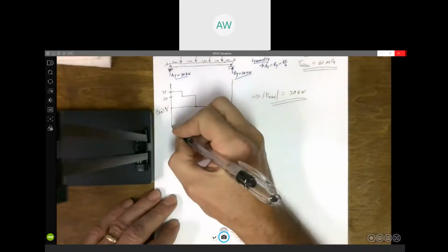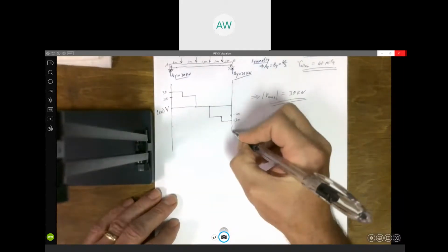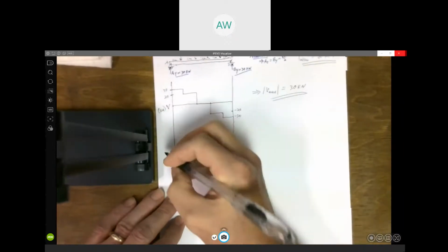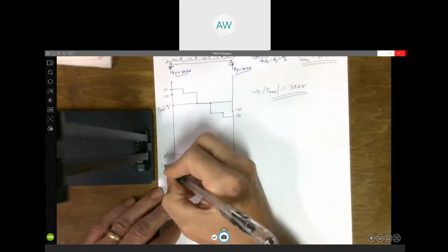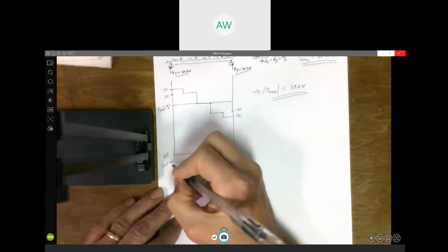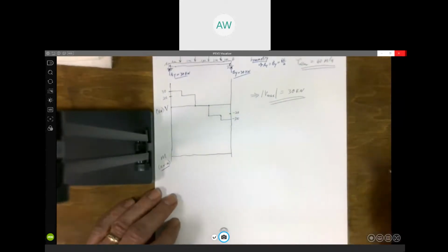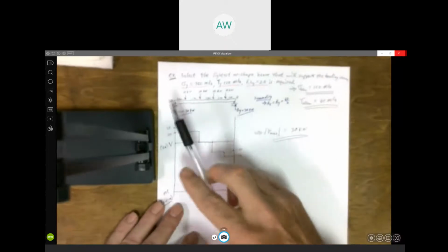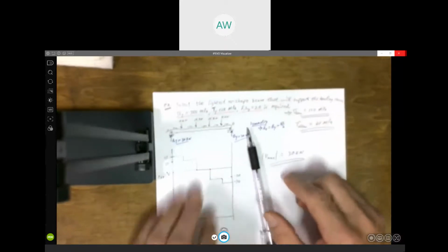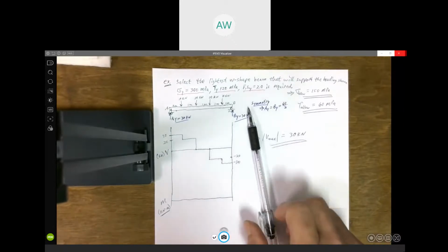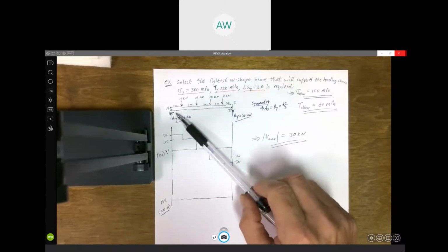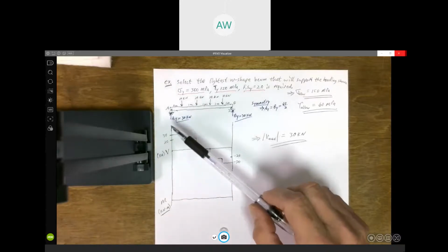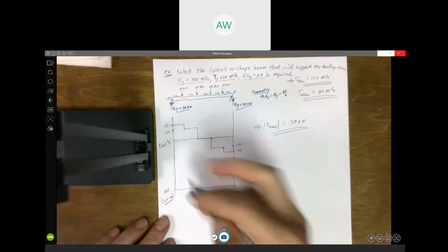All right, now to construct our moment diagram, this is our moment. These are kilonewton meters, my units here. I know from looking at my beam, if you look at this end of the beam, there's a pin support there. There is no moment applied. So the moment at this end is going to be 0. So it's going to start here at 0.